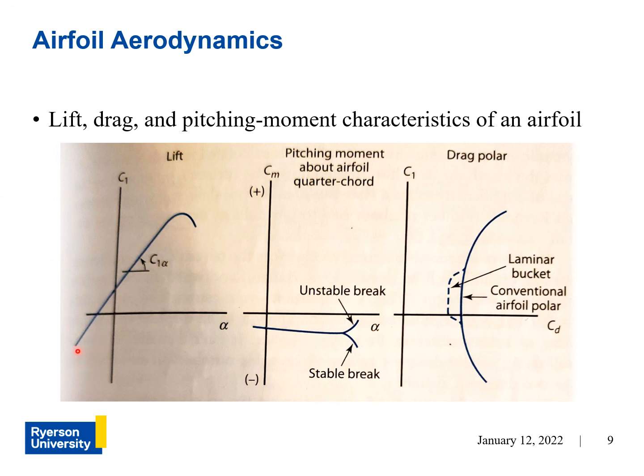Again, as I explained numerous times, the airfoil lift changes linearly with respect to the angle of attack until the stall region, in which that linearity disappears because of flow separation. Now the middle plot is the change in pitching moment with respect to angle of attack, and notice how it's near constant since we are taking our reference point about the quarter chord, or the aerodynamic center for a low speed thin airfoil.